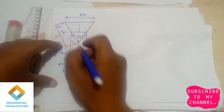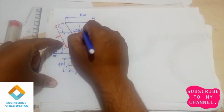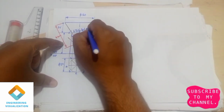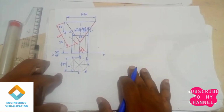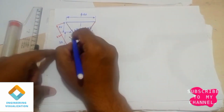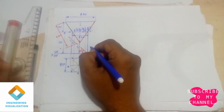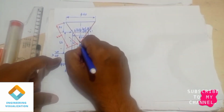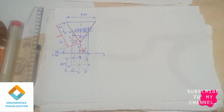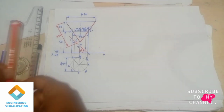Now write the namings. Here A dash, B dash, C dash, D dash and E dash are visible. H dash, G dash and F dash are not visible; those are written within brackets. Now we need to write the cut points. Cutting exactly line 1, 2, 3, 4. You can see wherever the section plane is cutting, right? So we are writing again here 6, this is 7 and this is 8. Part by part we are going to do the development of it. Now we have done the cutting also. Step by step we are going to follow it.